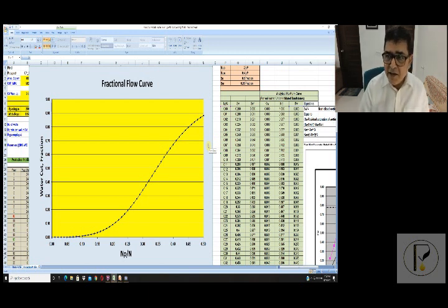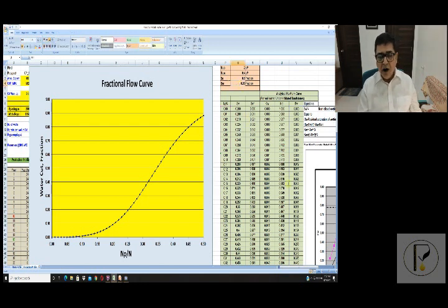So at the same instant, air is doing two things. Whereas the chemical was polymer first modifying the flow by regulating the mobility contrast, and surfactant coming later to reduce the residual oil saturation. Here, air injection is targeting both the viscosity of the oil as well as reducing the SOR number. So you can see the benefit, how EOR can change the fractional flow, how it can shift that fractional flow curve to the right.